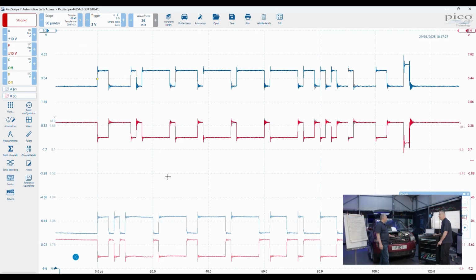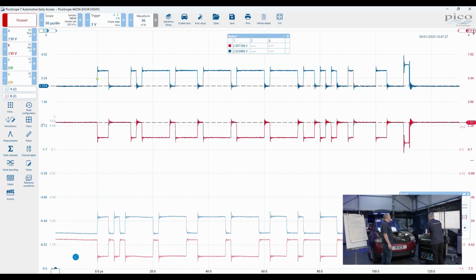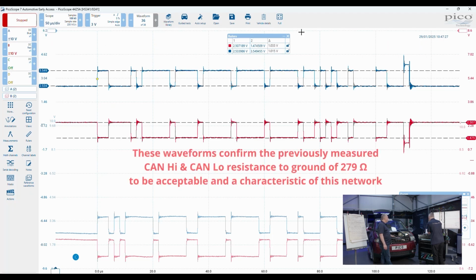So first impressions, Andy? Looks pretty similar. Yeah, let me put my glasses on. So we're interested in residual voltage: CAN high at 2.5, CAN low also, hopefully recessive, 2.5. CAN low switching down to 1.5, CAN high switching up to approximately 3.5. So we see that here in the ruler legend. I think all in all, are messages being sent? Yeah, at this stage you'd say there's messages on the bus. So with that, we will move on.